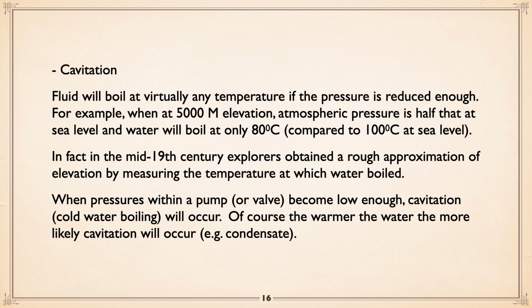Now, let's talk cavitation. Cavitation is not vortexing. Cavitation is the fact that fluid will boil at virtually any temperature if the pressure is reduced enough. For example, at 5,000 meters elevation, something like 18,000 feet, atmospheric pressure is half that at sea level, and water will boil at only 80 Celsius compared to 100 Celsius at sea level. In fact, in the 19th century, explorers obtained rough approximation of elevation by measuring the temperature at which water boiled.